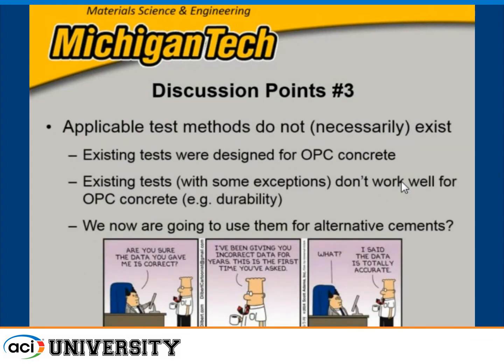Test methods. This was a huge issue. And in my opinion, I think it's probably the key issue with these materials. Applicable test methods do not, I put in parentheses here, necessarily exist. The existing tests that we have were designed for ordinary Portland cement concrete. And I think many of us would argue, I certainly would argue, that in many cases they don't work very well for that. Particularly when it comes to durability tests, we have a lot of tests that we use that are not that good a test.